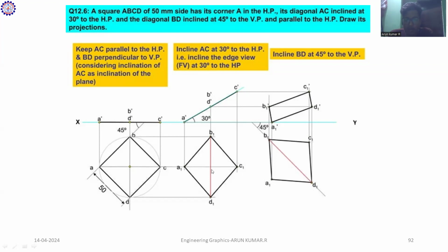Okay. So how to construct these A1 and C1? You have to take the compass, measure the distance, and cut the arc by using the compass. Similarly, you construct C1 and A1. After constructing this diagram, that is a tilted square, also called a diagonal square.